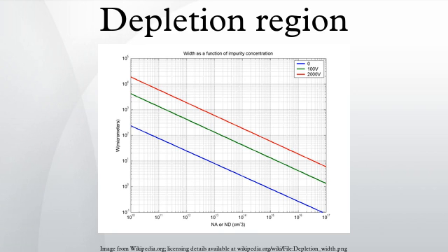Suppose that the semiconductor initially is charge neutral, with the charge due to holes exactly balanced by the negative charge due to acceptor doping impurities. If a positive voltage now is applied to the gate, which is done by introducing positive charge Q to the gate, then some positively charged holes in the semiconductor nearest the gate are repelled by the positive charge on the gate, and exit the device through the bottom contact.